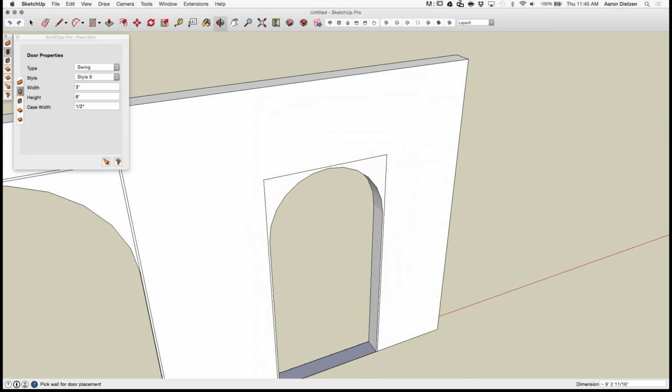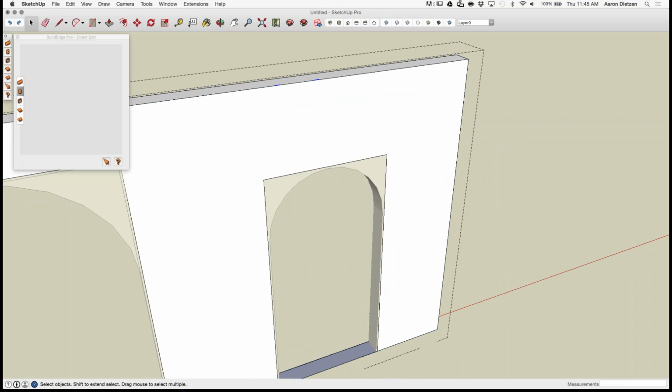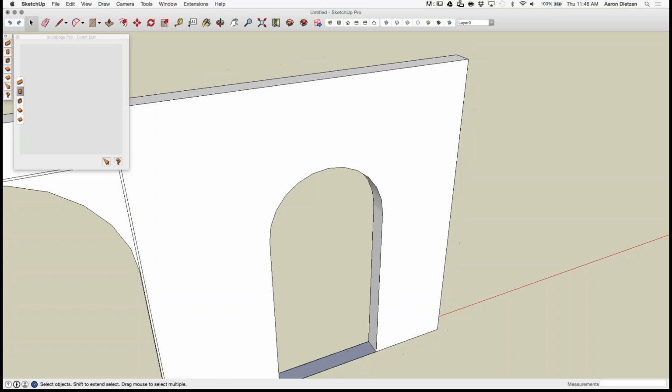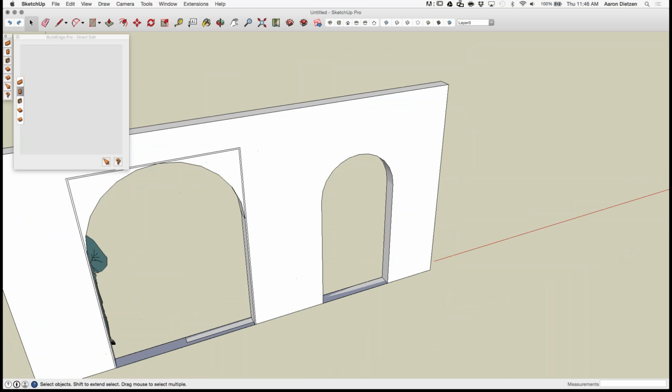So if I wanted to, at this point, I could select the wall, which is just a group. I could open that up and use Shift Erase or Select and Hide to hide these three walls. Hide, not delete, a very important difference.